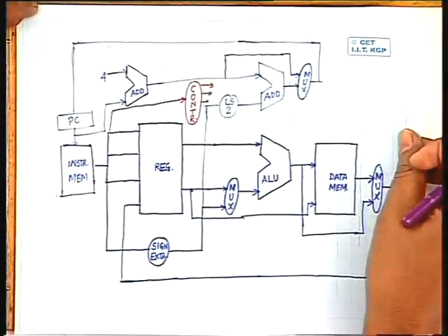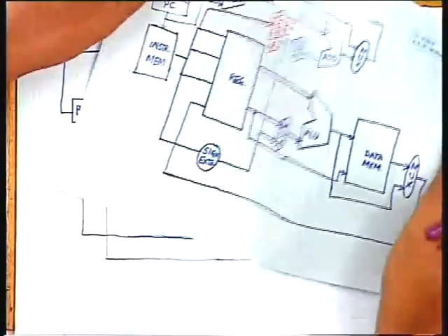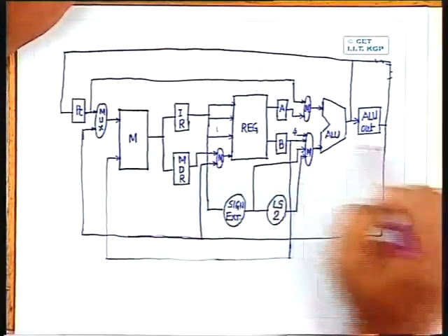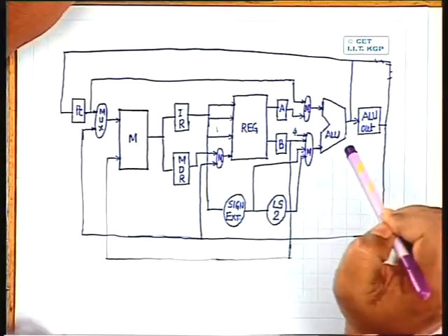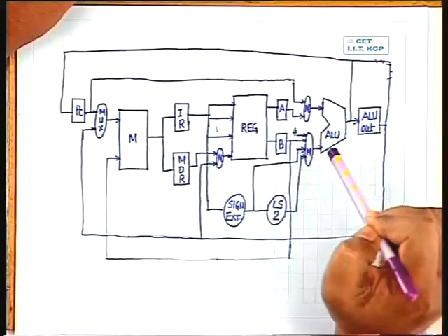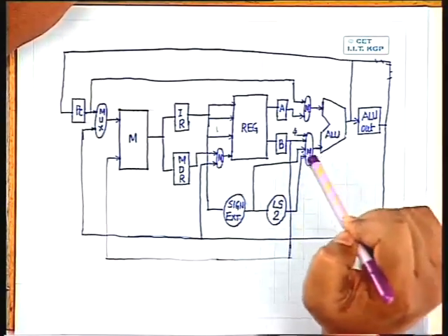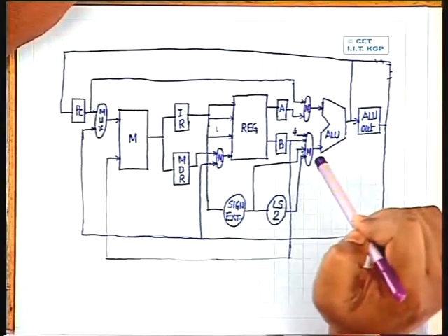So an improvement over this that we have tried is, instead of a single cycle implementation, we can go for multi-cycle implementation. In multi-cycle implementation, what we have done is we have broken this data path into a number of steps. So there are 5 different steps, and in addition to that, we can reduce the duplication of data units.